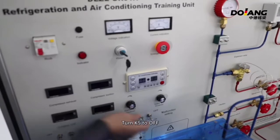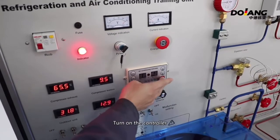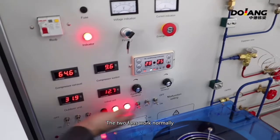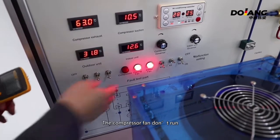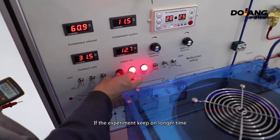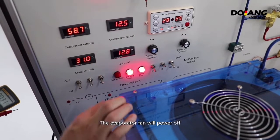Now do the fifth fault experiment. Turn K5 to off. Turn on the circuit breaker. Turn on the key switch. Turn on the controller. The two fans work normally, but the compressor fan doesn't run. If the experiment keeps on for a longer time and you don't turn on K5, the evaporator fan will power off.